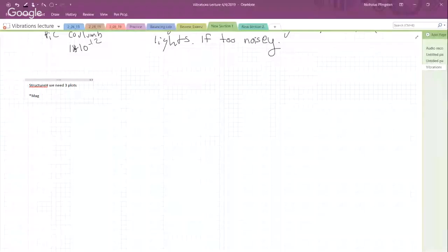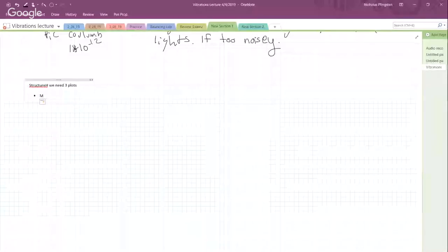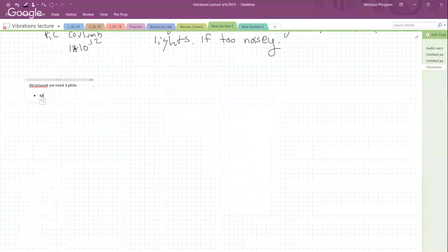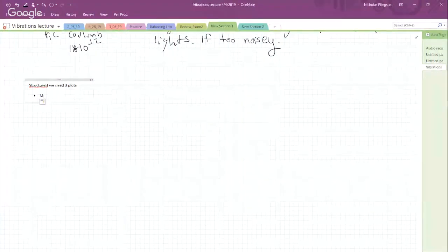So we see that our frequency is 1751. Our magnitude is 18.98. So we take that 18.98 multiplied by 0.707. That gives us our bandwidth. We hit the negative sign. It pulls us back. So that's a plot that we want to save right there.